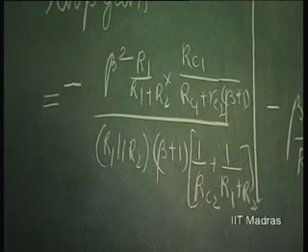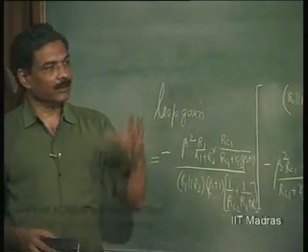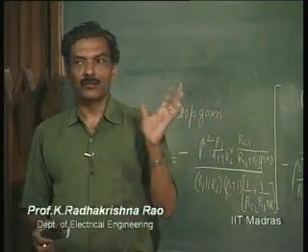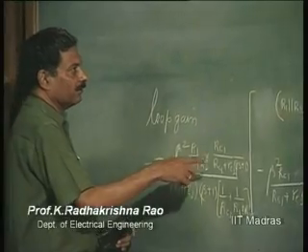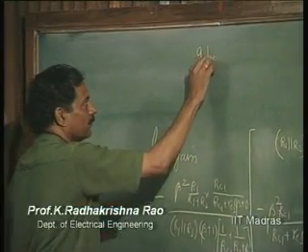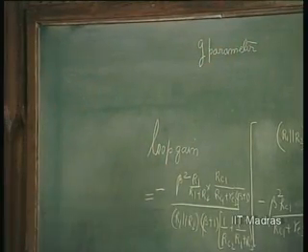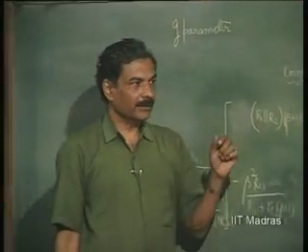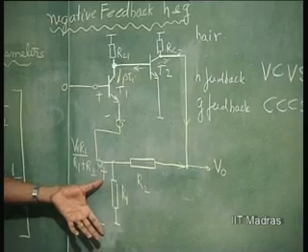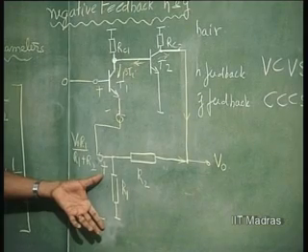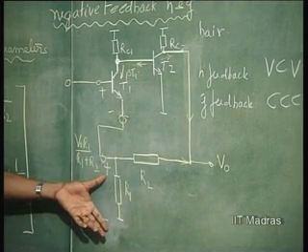Now, we can once again establish, after feedback, what the input impedance, output impedance and forward transfer voltage gain is going to be for this. Obviously, the parameter of interest will be the G parameter of the structure, and in the G parameter we can establish that the forward transfer voltage gain has to be determined by only the passive network. The feedback factor is R1 by R1 plus R2, and the gain has to be 1 over the feedback factor. That is what we have established if the loop gain is very high compared to 1.